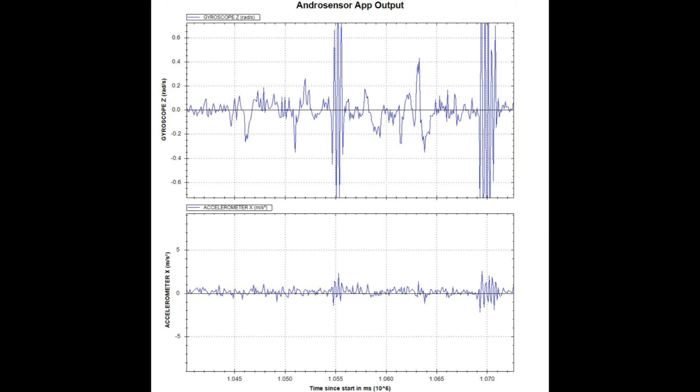But then it gets interesting starting at 1,057, where you can see it's kind of all over the place. At first, the steering wheel seems to be going up, which is to the left, which is a left lane change, but then it moves to the right, settles, moves to the right again, moves to the left, and then goes way up, moving to the left over 0.4 radians per second, then goes down again to the opposite direction. So this thing is ping-ponging around.